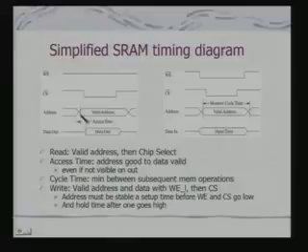The address is provided on the bus. The decoder would be typically part of the memory device itself for selecting the row. So once I have selected the corresponding memory module and I have provided the valid address, the row would be selected. And after that, you will be expecting the data. So this is the time difference between the address becoming valid and you receiving the valid data.